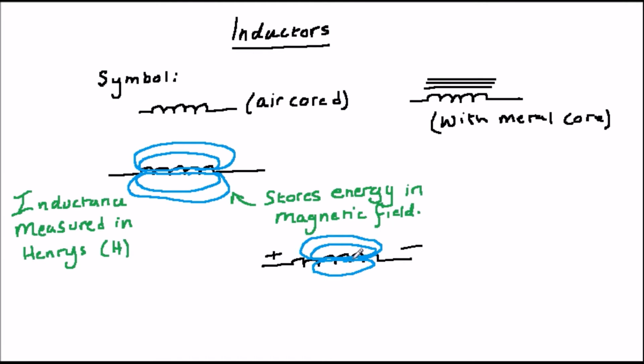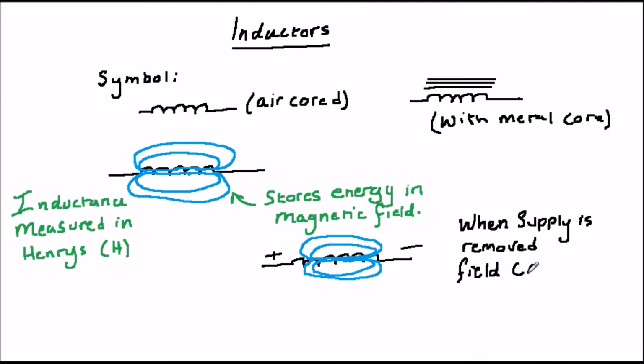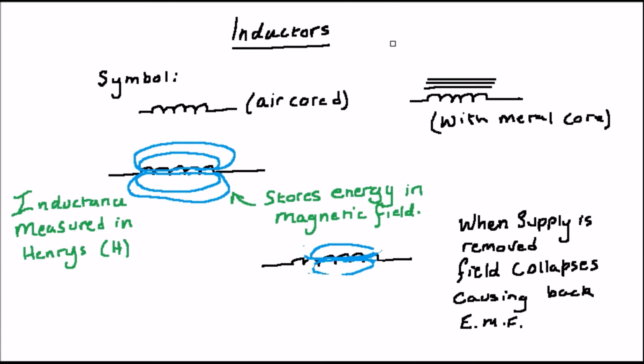One difference between an inductor and a capacitor is that a charged capacitor will retain its charge when you remove it from a circuit. However, in an inductor, without a current to sustain the magnetic field, the energy just disappears. The amount of energy stored depends on the inductance. This is equivalent to capacitance in a capacitor and is measured in henries. Again, rather like a capacitor in farads, inductance is a rather large unit, and so you're more likely to see millihenries or nanohenries or microhenries.